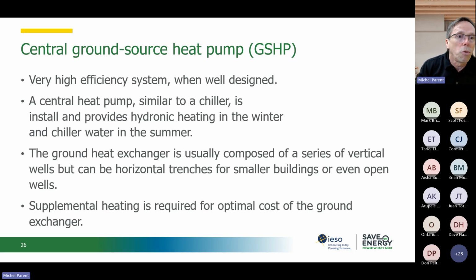So you don't have to worry then about, do I still need to have natural gas, or how am I going to provide for that supplemental heating? Is it going to be an electric boiler, in which case my demand might skyrocket and it would not be economical to have it? Well, the central ground source heat pump doesn't have that problem, because it takes its energy from the ground, which is not really impacted significantly by weather changes. So even if it gets really cold outside, you still have that same capacity.